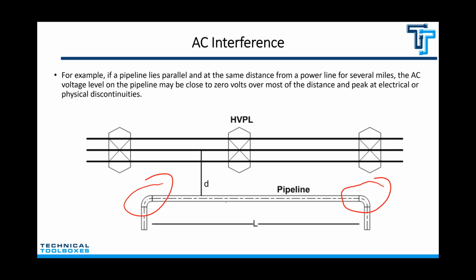And often, if you have a long pipeline running for a long area, a lot of time your volts will be 0 throughout a lot of that pipeline. Because you've got current, it's all current going through the steel, and it's not any voltage. Remember, the voltage is always where that current wants to get off the pipeline, go back to the soil to get back to a source. AC is no different than DC. All current has to get back to where it came from. Okay.